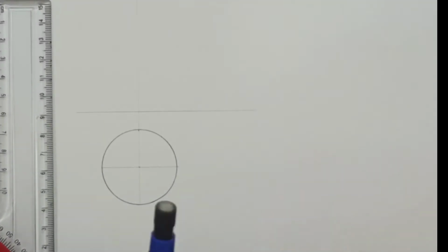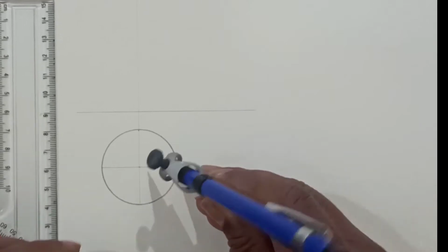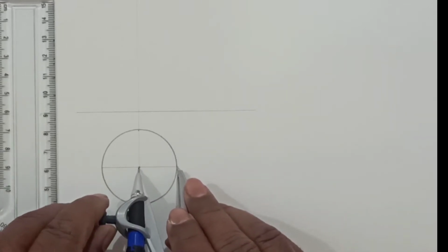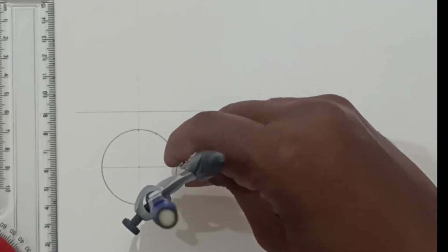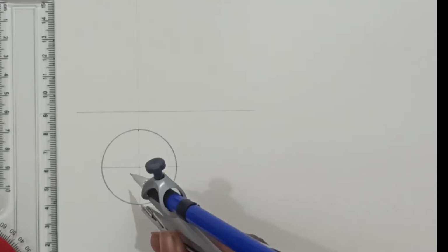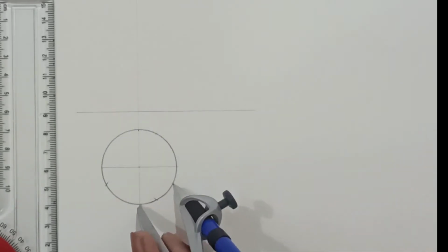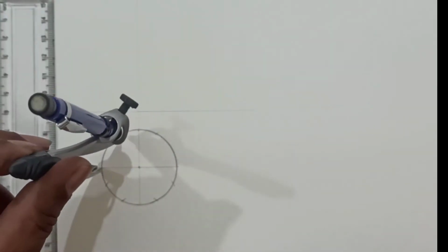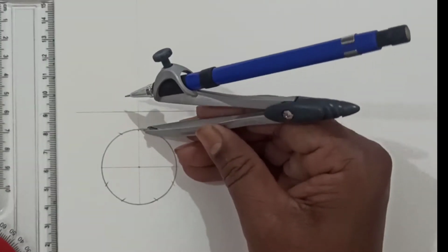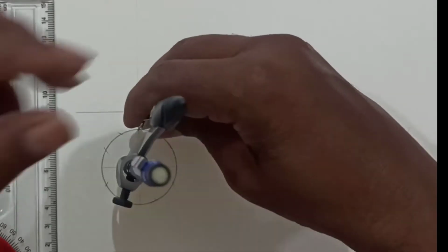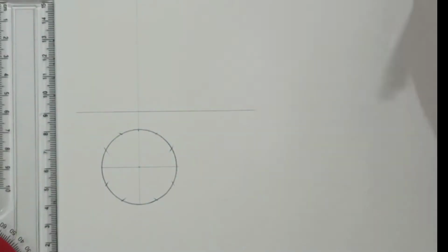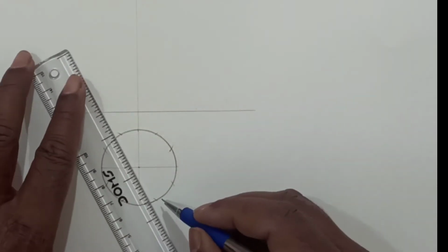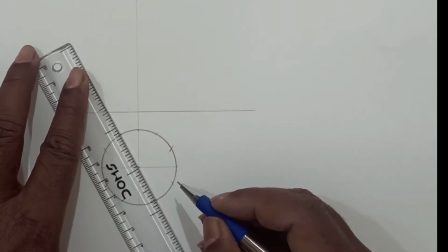The axis of a cone is perpendicular to the HP and the base is resting on the HP. So initially draw the top view, in which we have to draw a circle representing the base of the cone. Now we have to divide this circle into 12 equal parts so that we can draw the generators, which will assist to draw the sectional top view, the true shape of the section, and to locate the cutting plane.